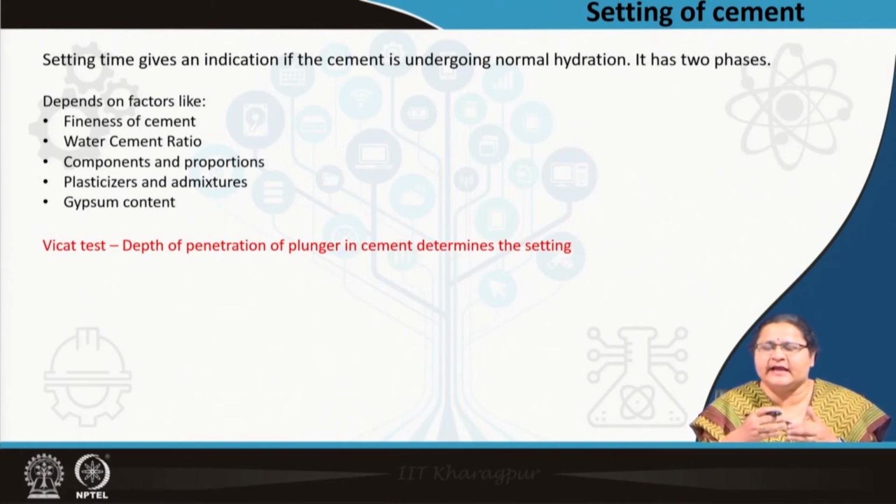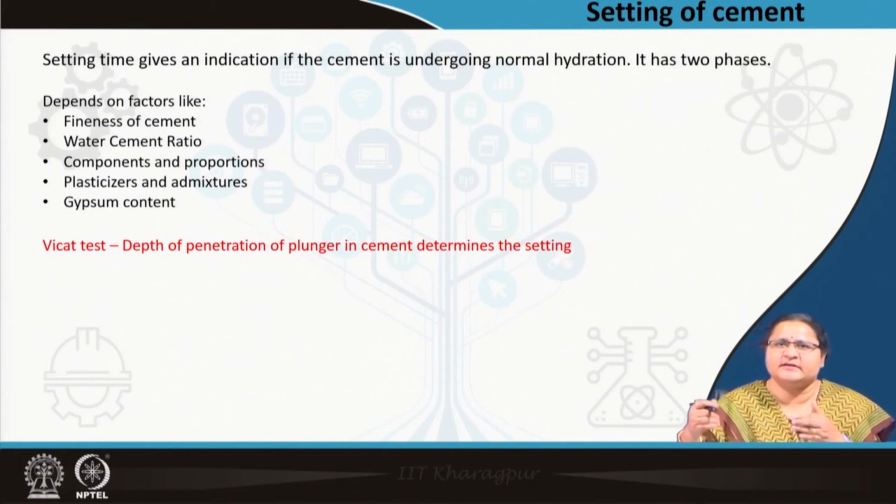That is, their reactions or hydrations happen faster and in the very beginning, and gradually the time increases and the hydration still continues, and that is why during curing you always need to keep water. Yes, the water is mixed inside it, but gradually the strength gain happens.